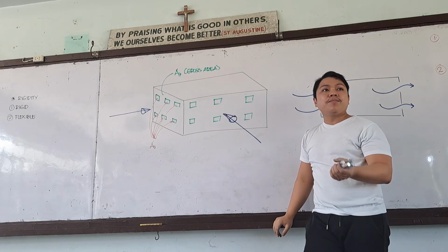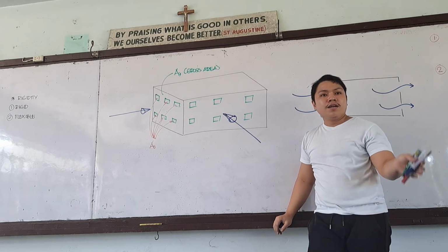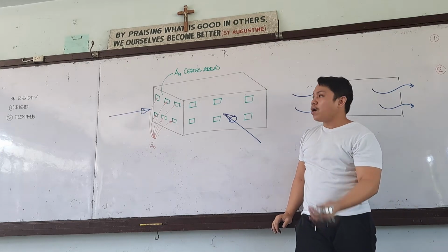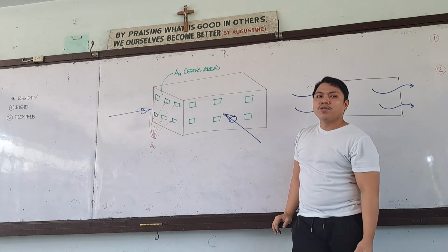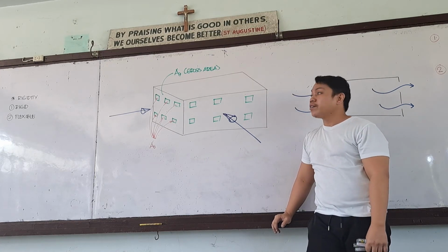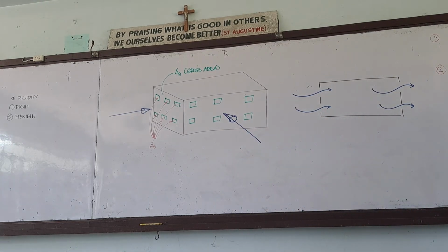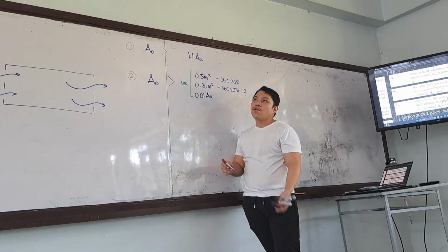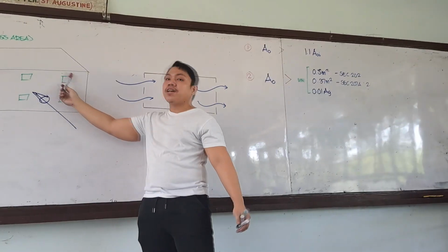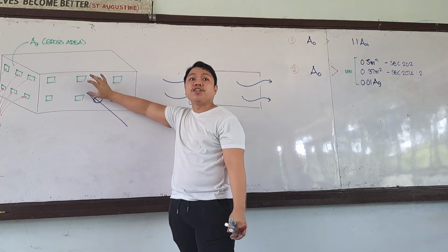More likely, there are no open buildings among residential or commercial ones. Usually open buildings are covered courts. You should satisfy both conditions for open. If one side of the building is not classified as open, you can classify it as partially enclosed.